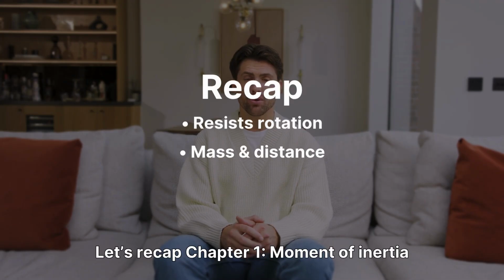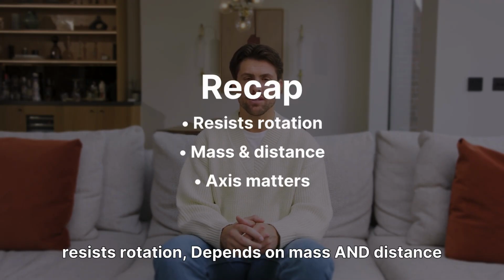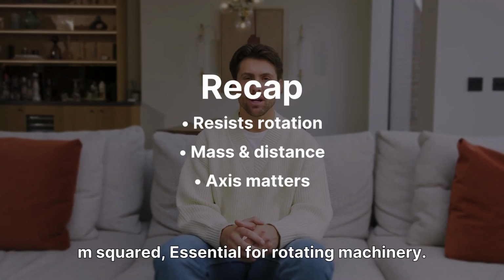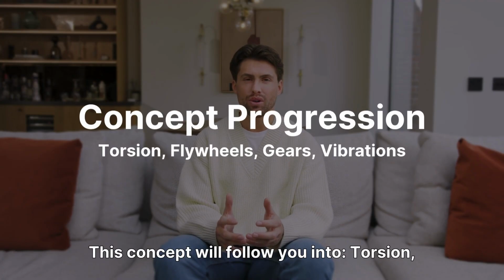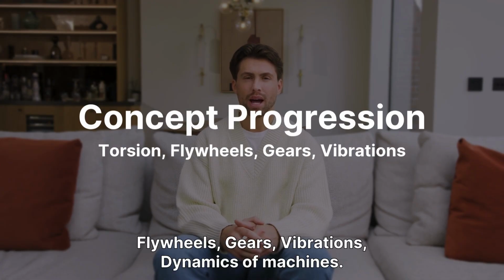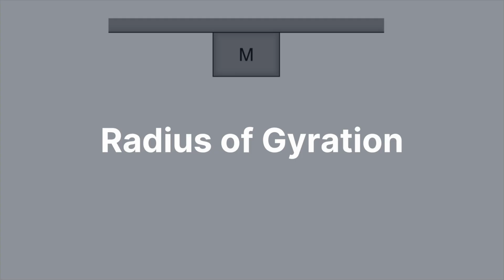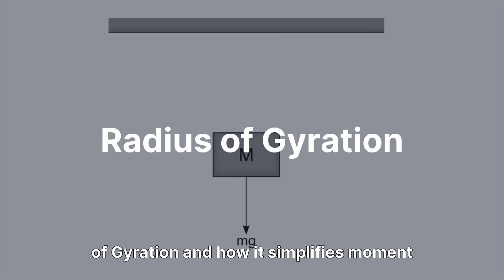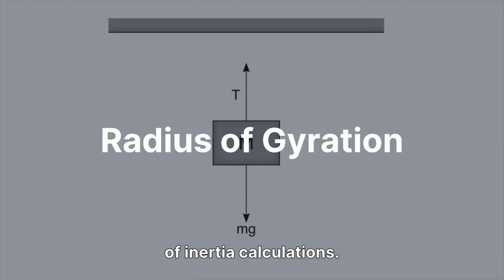Let's recap Chapter 1. Moment of inertia resists rotation, depends on mass and distance from axis. Axis matters. Units are kg m², essential for rotating machinery. This concept will follow you into torsion, flywheels, gears, vibrations, dynamics of machines. In Chapter 2, we will explore radius of gyration and how it simplifies moment of inertia calculations.